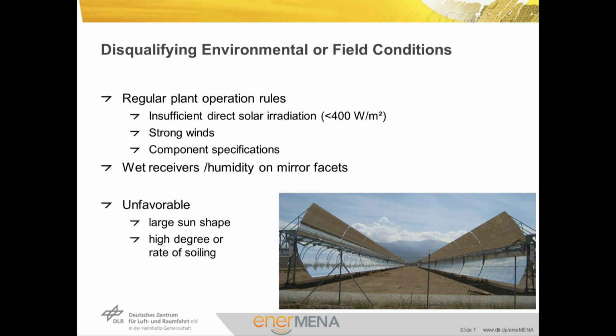Evaluating such test data leads to lower values of system efficiency compared to similar test conditions with small sun shapes. Furthermore, a high degree of soiling might not be representative for actual field operation. Especially, irregular soiling patterns are difficult to quantify in terms of average effects in the field. High rates of soiling during testing, constantly decreasing the field's optical potential, imply the need for frequent cleanliness measurements.